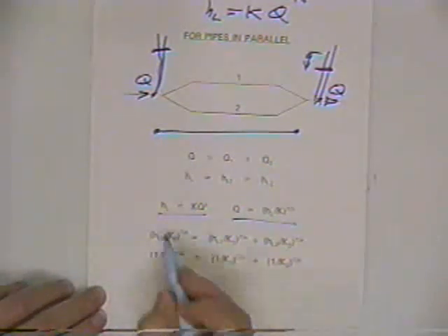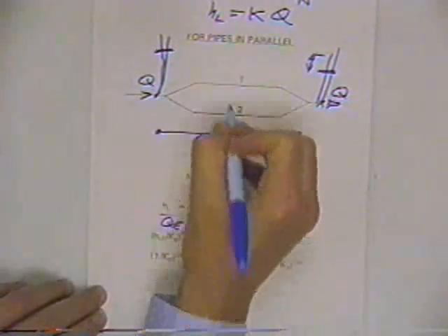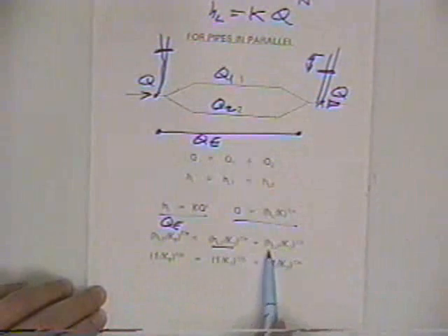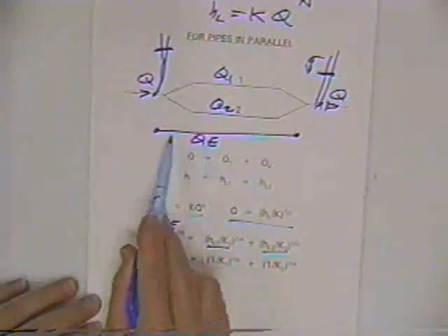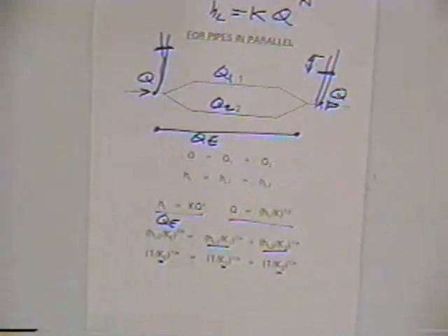in the equivalent pipe, this is some Q here, would just be this Q plus that Q, and that Q can be expressed in terms of the head loss in that pipe, and that one expressed in terms of head loss in that pipe. All that's just to say that one pipe with that K is equivalent to those two pipes with those two Ks related by that expression. And so for pipes in series, pipes in parallel, we can have those basic relationships.